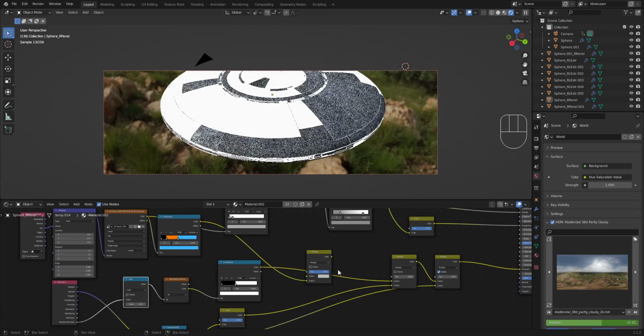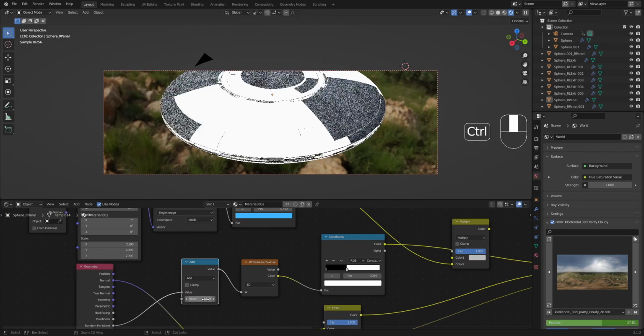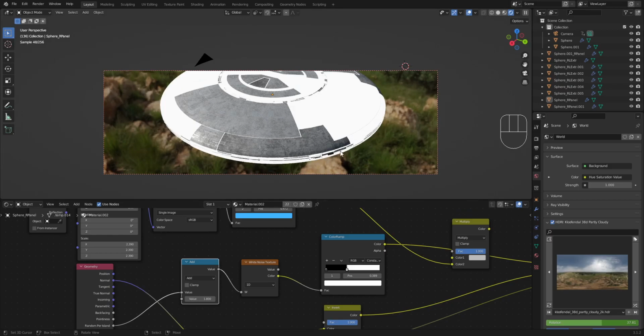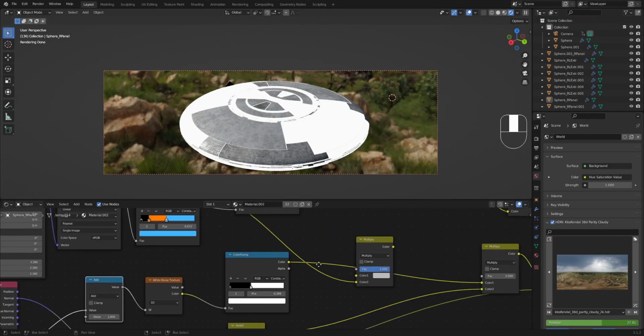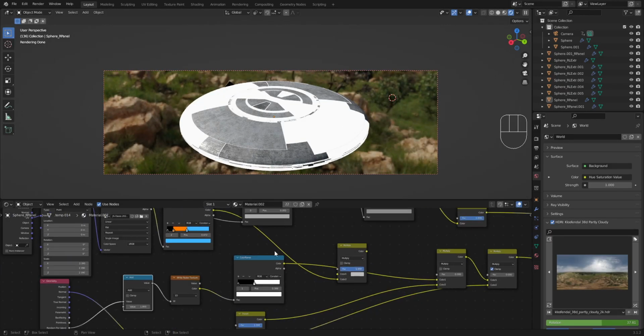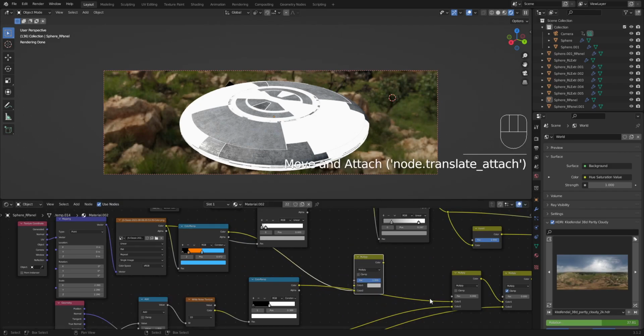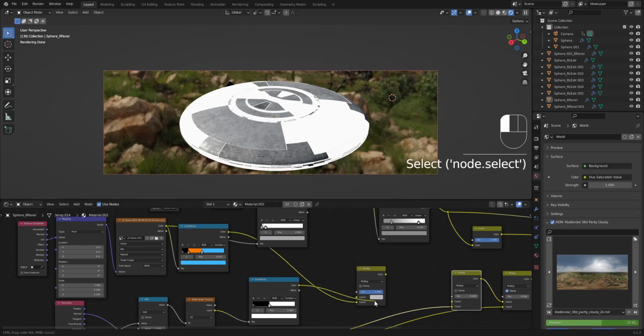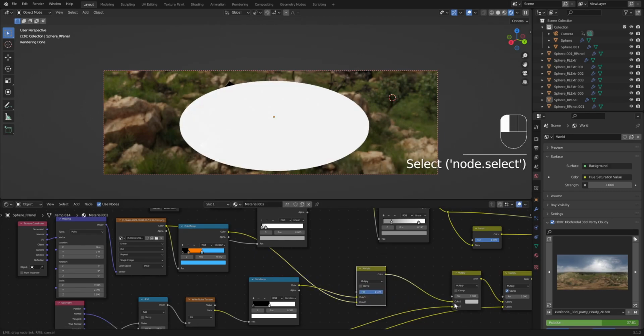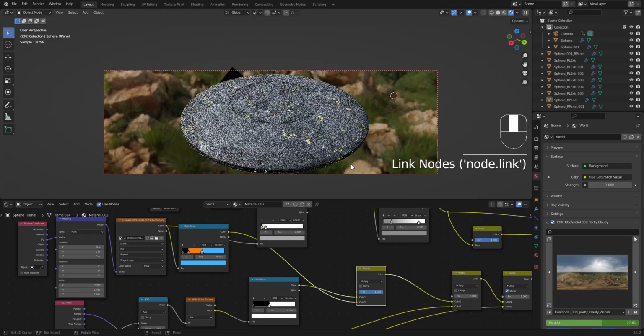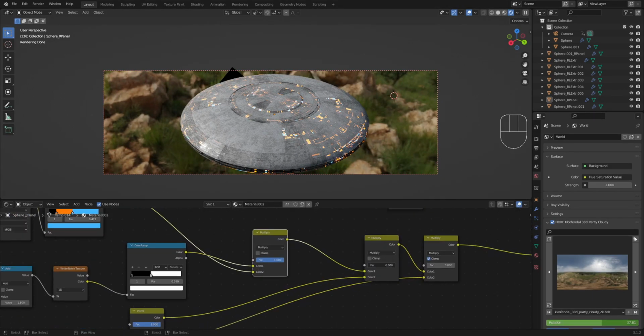We turn this off, and then this result, this alpha, we're going to multiply with this color here, the GS placement texture. So set this up in the color one input there, and get rid of the lights in the positive Z and the negative Z axis.